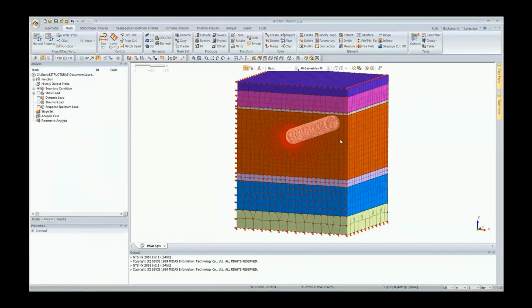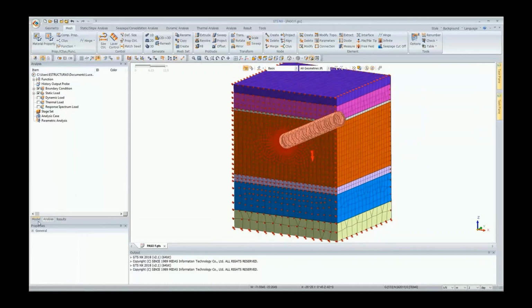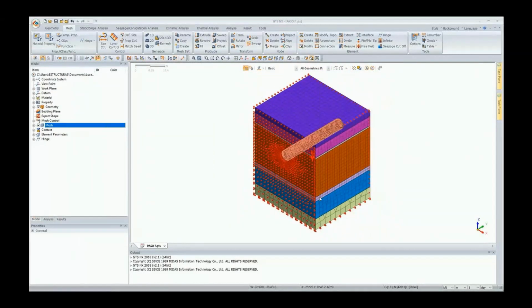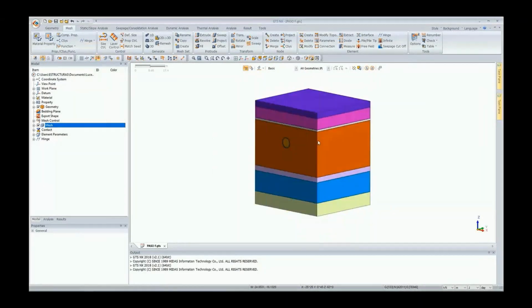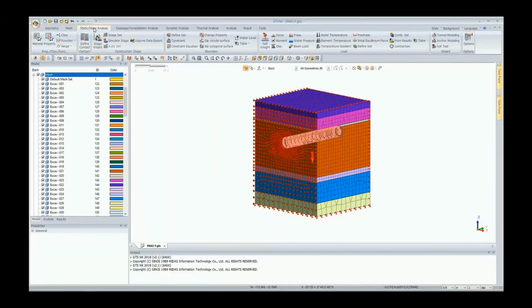Here I'm just giving a quick inspection to everything activated. We see the represented loads, boundary conditions, and change of material properties. So we're basically done with the model. Now I have to define the construction stage analysis, for which we have a wizard. And again, this wizard can be taken advantage of so long as the sequence of these tunnels and excavations or whatever is in the right order. So we can just go to the wizard under the static slope analysis. We see here the construction stage wizard.